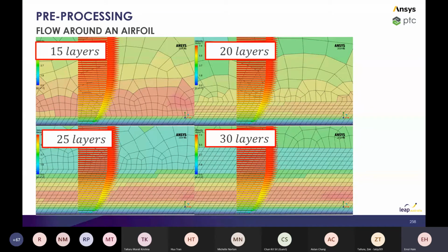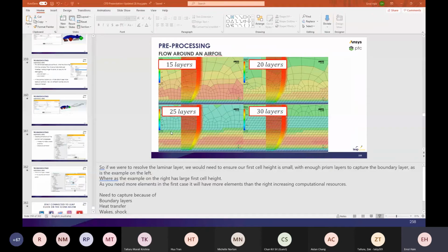So you're inflating each mesh inflation layer from that starting point. These are just a mesh strategy that allows you to get mesh elements that are aligned with the flow direction close to the wall. And that's just the best way that we've found of resolving boundary layers when using RANS models.